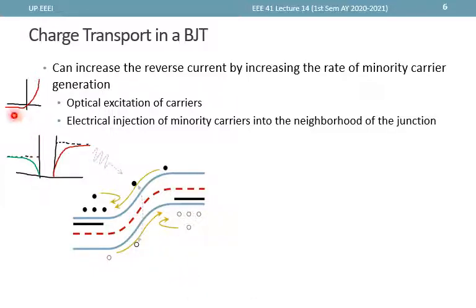And what actually happens to the IV curve is you are getting more current for the same amount of bias that you apply, and therefore this technically shifts the IV curve of your device. And so with this behavior, the changing current based on light, photo detectors can detect light.